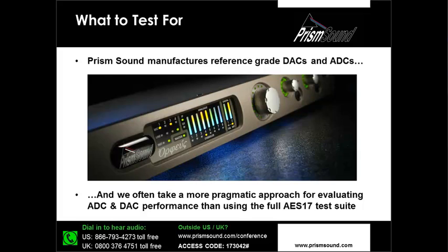And it would be fair to say that we very often take a slightly more pragmatic approach to evaluating our converter performance when we're looking at iterative design changes on the bench than running through the complete suite of AES17 tests every time we make a minor change to a circuit design. We tend to, as I say, be a little bit more pragmatic about our testing.